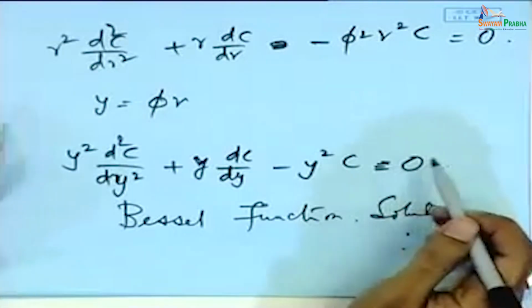If there is any question on the part that we did today, let me talk conceptually for 1 minute about what we did. The whole lecture pins on this idea of the pseudo homogeneous model. The basic idea is that a pseudo homogeneous model is really for a heterogeneous system where there are different point sources or sinks of reaction, and you can do an averaging if two conditions hold.